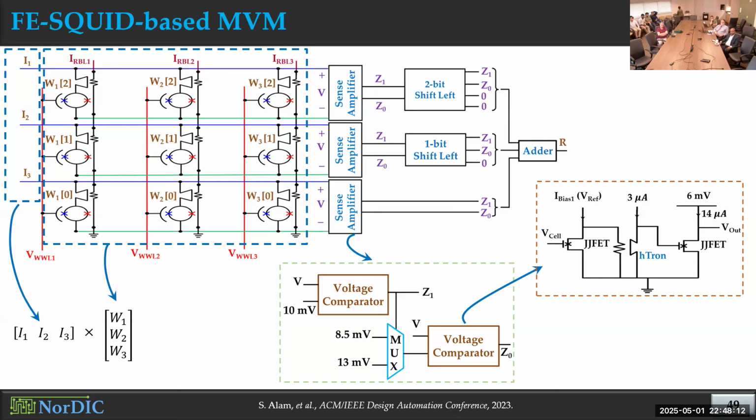And again, after storing the weights in this memory system, which is the write operation, when we perform this matrix vector multiplication, we just perform the read operation again and again. And as you remember, in this memory system, we use that superconducting portion for the read operation, which is highly energy efficient. That's why we have estimated here that to perform 1 bit of matrix vector multiplication, we need around 5 attojoule of energy, which is a significant improvement compared to any other memory technologies that we have.